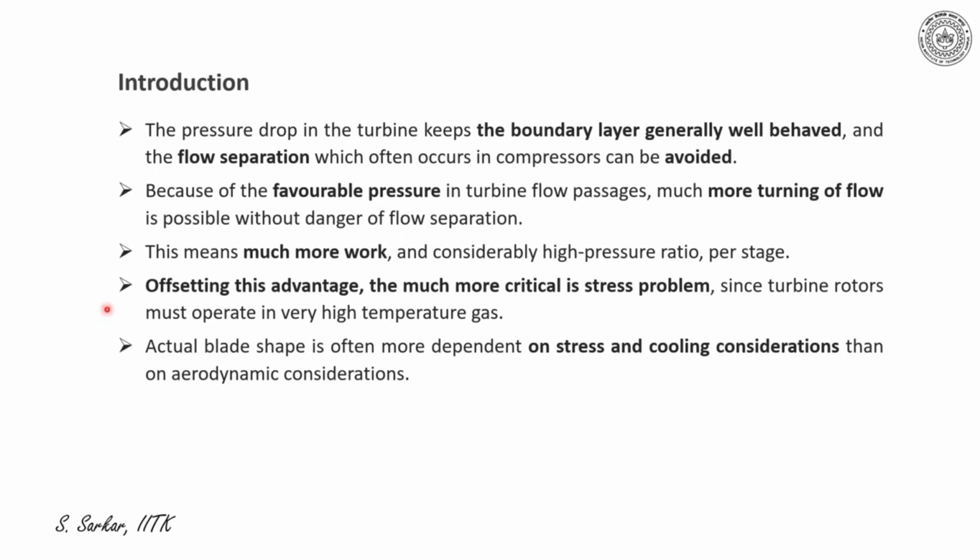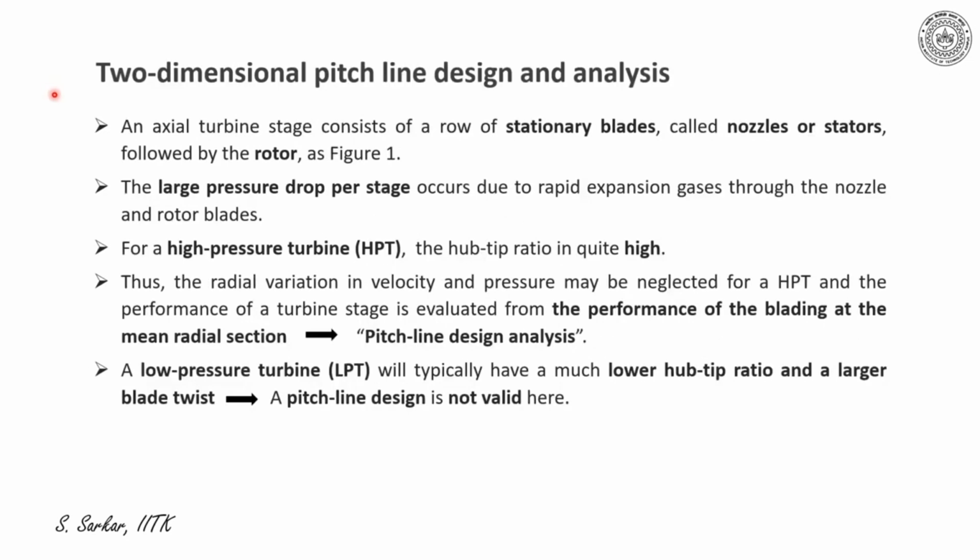Offsetting this advantage, much more critical is the stress problem, since the turbine rotor is exposed to high gas temperature. Furthermore, the blade shape here is often more dependent on the stress and cooling considerations than the aerodynamic considerations. I'll explain here the two-dimensional pitch line design and analysis.